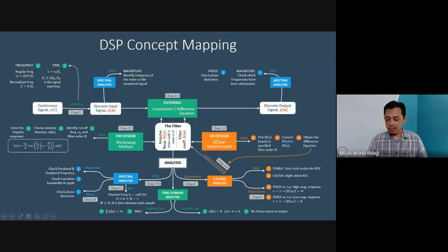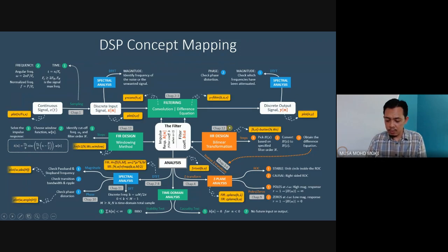Okay, all right. So these are the MATLAB functions that you can use even in your assignment. I think most of the groups already use either FIR1, or you can use this one, butter. You use FIR1 to get Hn for an FIR filter. You can use butter to get the filter coefficients B and A, right? So that's when you are designing the IIR filter.